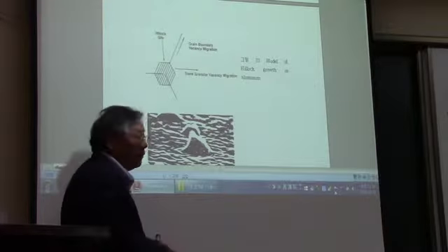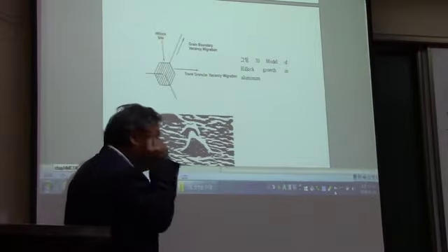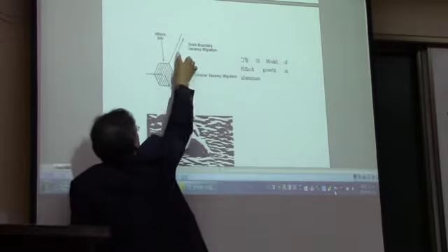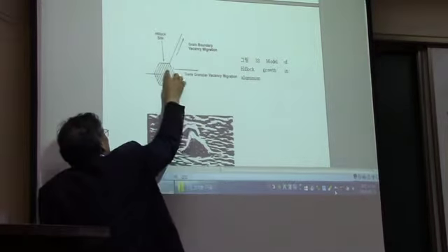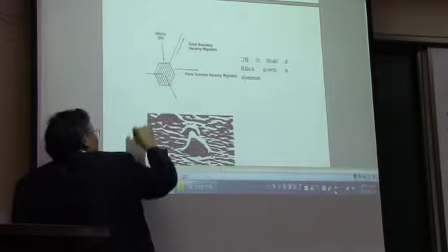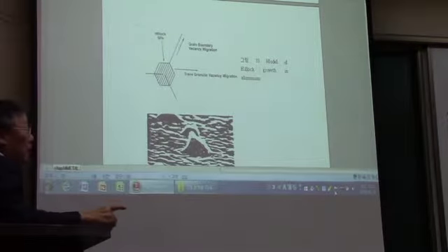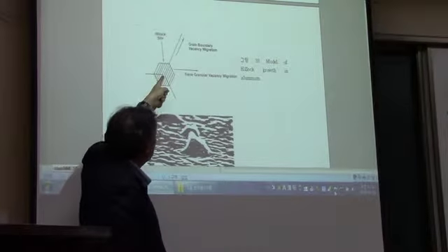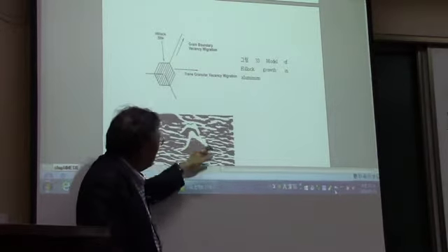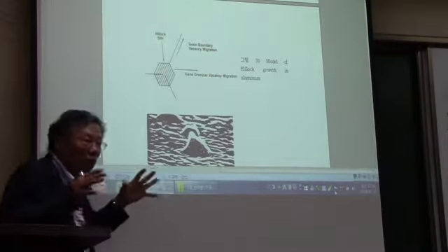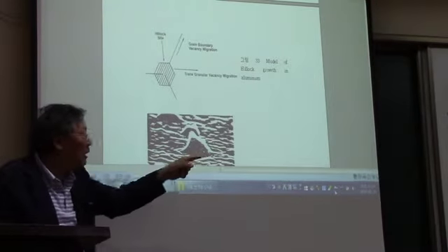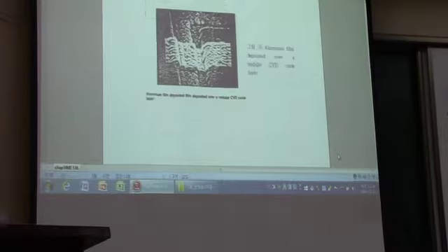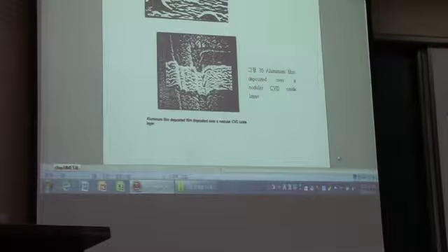But if you have the situation the other way around, in other words, the atoms are moving along these two directions and then there is one exit, then you are going to have accumulation of atoms at this triple point, and you're going to have a huge rock in there, and we call that a hillock. And this hillock is really bad in lithography, as you can see here.